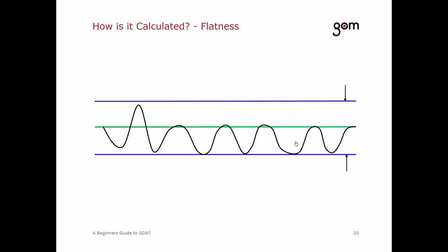The width of the tolerance zone is the given tolerance. The result value of this check is then the highest value from the center plane. Very important here, all points must be within this tolerance zone. Again, the flatness of the entire plane ensures the function. If only one point sticks out of this zone, the tolerance check is failed. So what you see in your result is the worst case error regarding the form, and it is therefore again important to measure the entire plane regardless of your measuring system.